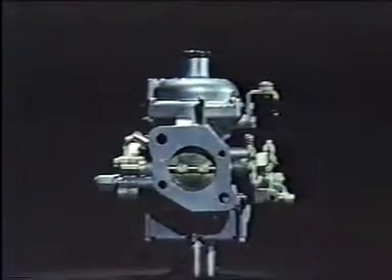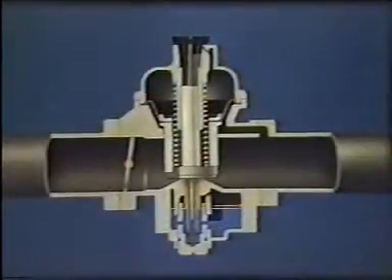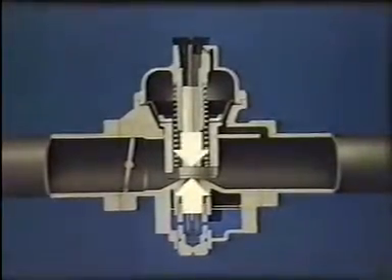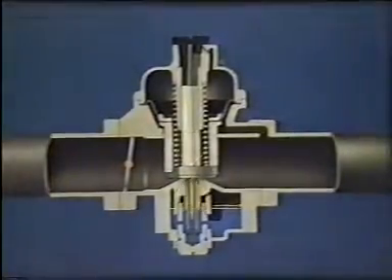There is another type of carburetor. It is called a variable jet carburetor. One side of the venturi is replaced by the bottom of a piston, which moves up and down in a finely machined cylinder. When the engine is at rest, the pressure on both the underside and top side of a piston is atmospheric, and therefore equal.